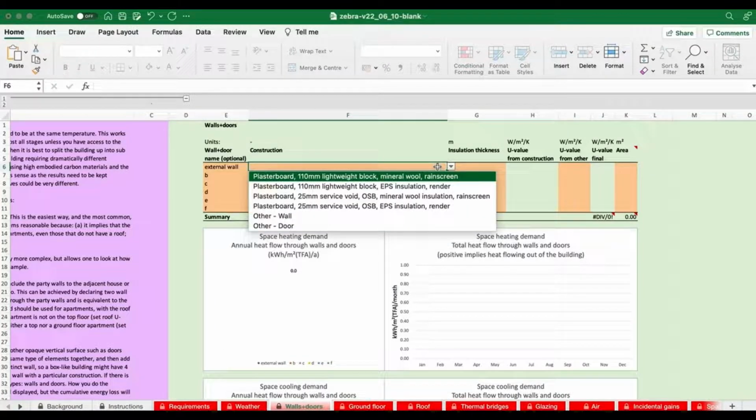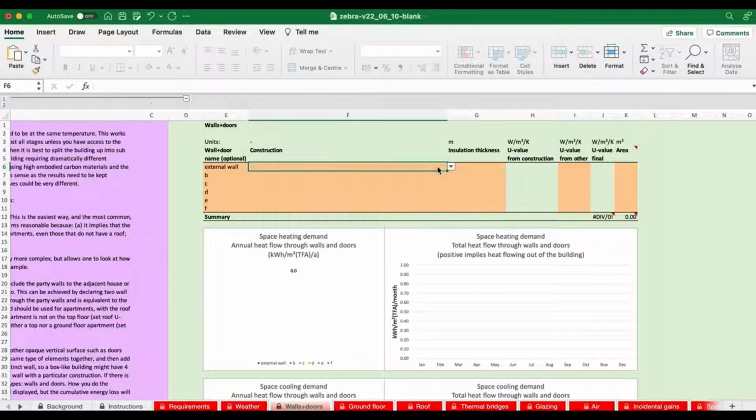If you do, this will pick up U values and things for you, but we actually know our U value. So we leap straight away to our U value, and we type that in as 2.46, looking at table 1 in the document. Okay. And the area of the external walls, which we've worked out by hand, is 3905.